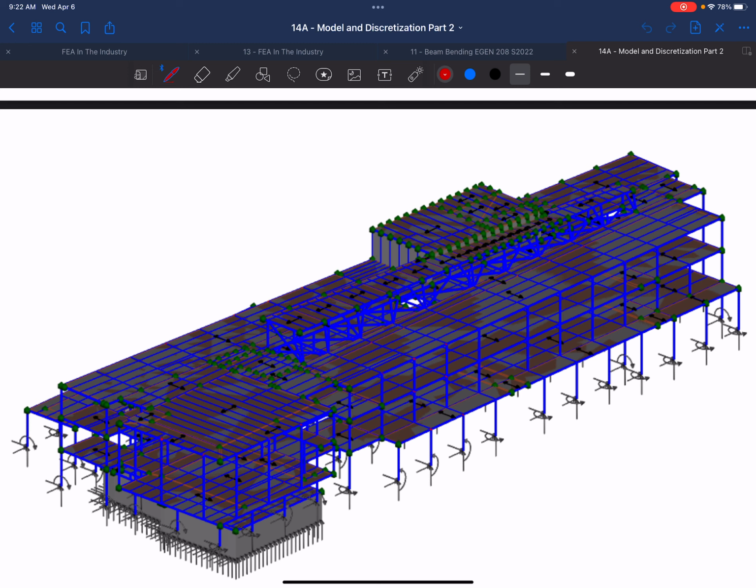The other benefit of doing this is we could use this gravity analysis for vibrational analysis, because VA will go through and look at your eigenvalue, eigenvector problem, right? It has mass associated with all of these members. So then you can figure out the natural frequency of this floor and check it versus the excitation of people walking, or aerobics. I mean, on the 3rd floor of this, because the gym fell down, they were doing aerobics, right? So that might have influenced other people in other rooms if the floor wasn't looked at for vibration, right? Okay.